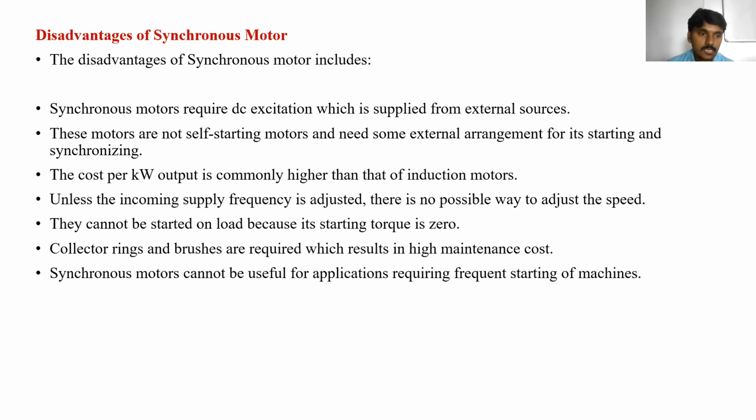There is no need for any external supply to the rotor circuit. That is one of the main advantages of the induction motor. But in the case of the synchronous motor, we need one more extra supply, that is the DC supply, for exciting the rotor circuit. Okay, that is the drawback of the synchronous motor.